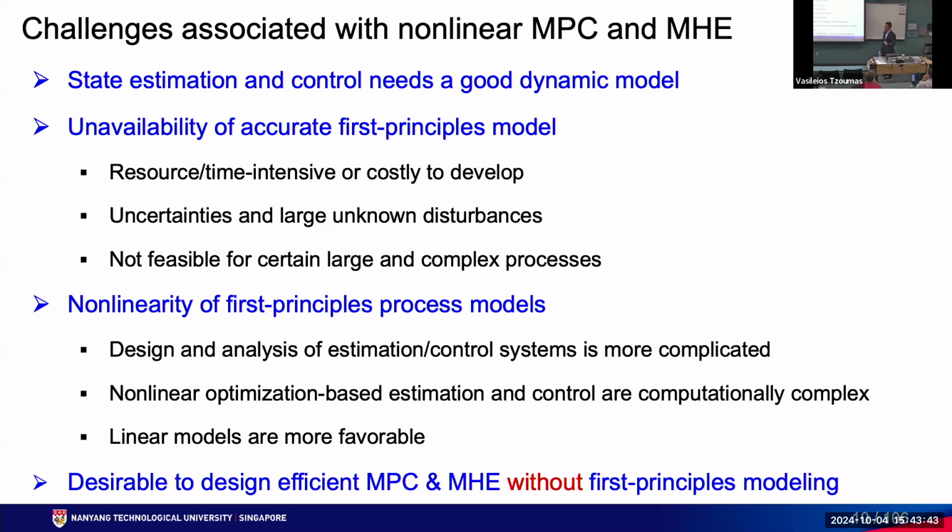It's not an option, okay? And another issue is the nonlinearity of a first principle model. Because if we choose to use physical knowledge, it must be nonlinear. Based on the thermodynamics and the mass and energy balances, it will be nonlinear for sure. But this will pose a limitation to efficient implementation of the optimization because of the non-convexity.